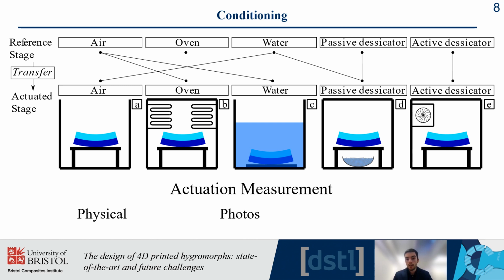You take an image, then you plot a circle around your specimen, and then you measure the curvature of this circle. And the last technique is what we call point of interest. It's basically when you position little points of interest on your specimen, and then you take a video and track the position of these points through space. Then you obtain the parameter that you want, a curvature or a deformation or a displacement, depending on the actuation, by post-processing the video.